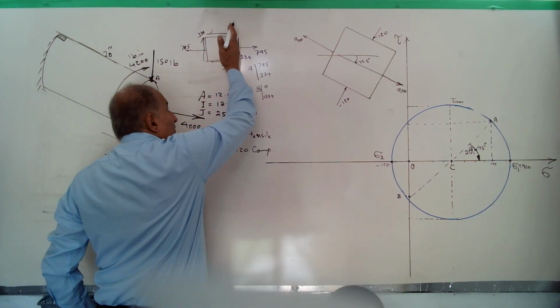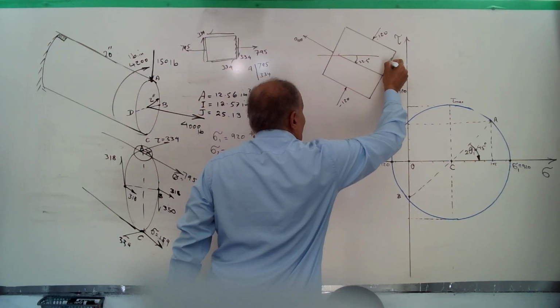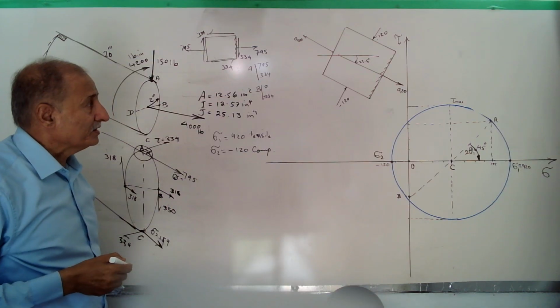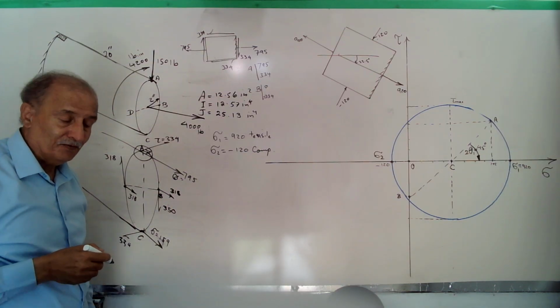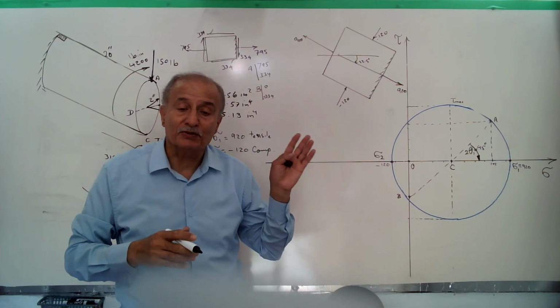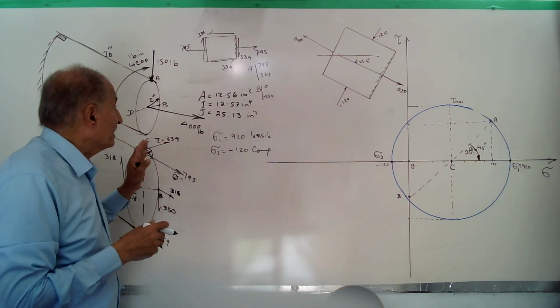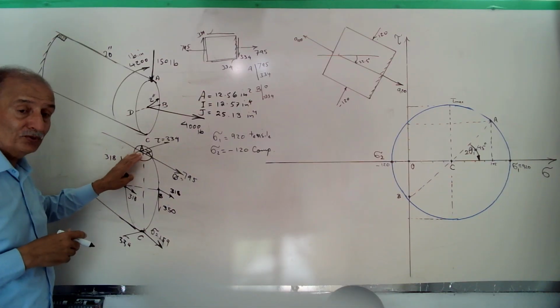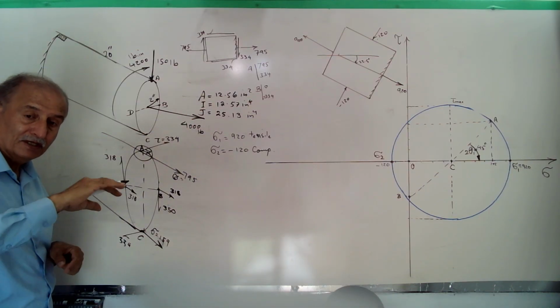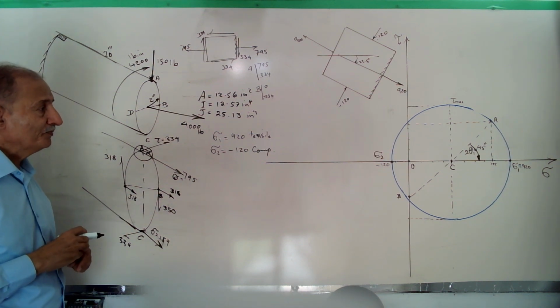Then this surface rotates to this state, and the normal stress becomes maximum inside the material. Any particle which is at 22.5 degrees with respect to the particle that we calculated the stress on has the maximum stresses in the clockwise direction.